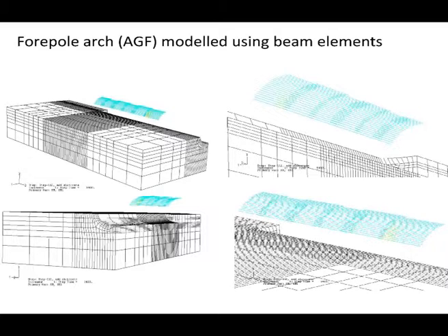And the forepoles are not there right at the beginning. The forepoles overlap 3 meters, I think, can't remember. So every time you get near the end of the forepole, there should be another set of forepoles. They have to install new forepoles. So the installation of the forepoles is sequential as well with the tunneling, and we have to model that into place. So the forepoling has to be modeled.